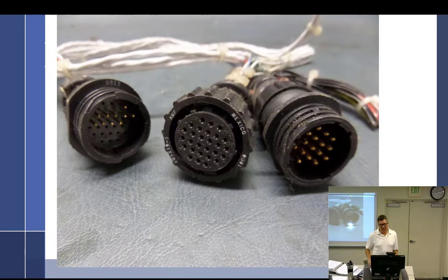Cannon plugs. I think one of the tests talk about which one is the positive and which one is the negative. So if you had a power coming in, see these pins fit into that right there, right? Which one would you want to be positive and have power attached to it right now? Which one would you want the ground to be on? Female. You'd want the power here, right? Why? Because if you drop a wrench on top of that, you got nothing to worry about. If all of these are hot or some are hot and some are ground, you're going to have a little welding project going on there. So not good.